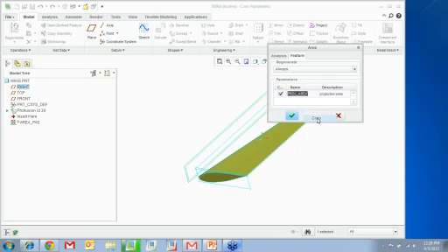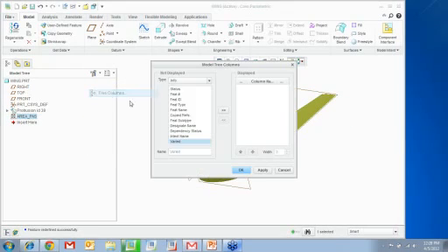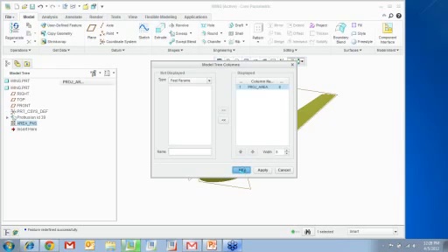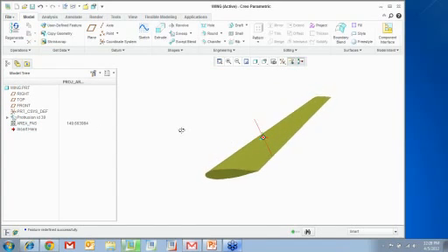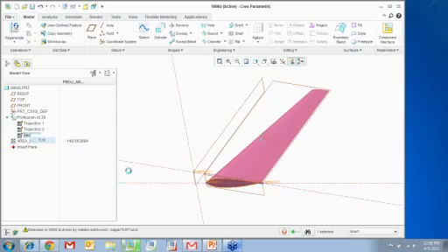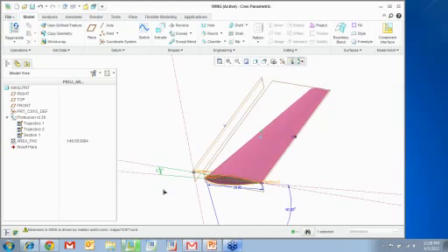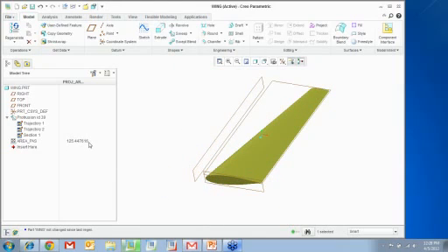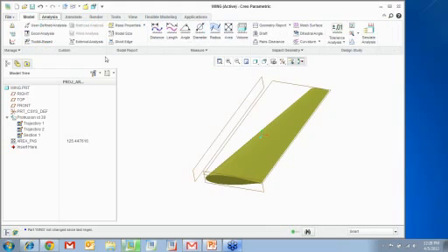This parameter has been created, and I can use the 3 columns feature parameters and use this projected area to calculate what it is. All right. So now I'm going to go ahead and edit. Say I want to edit that value to 5, and you can see how the projected area changes. Okay. All right. So that being done, I'm going to go ahead and click on the analysis feature.